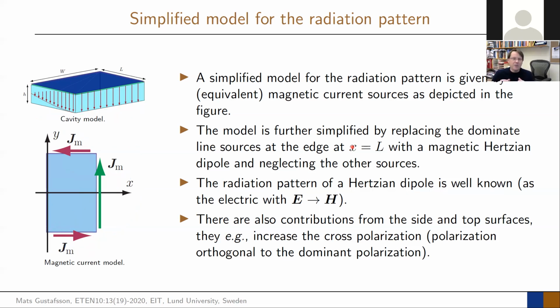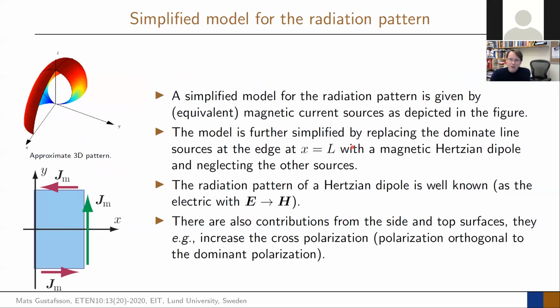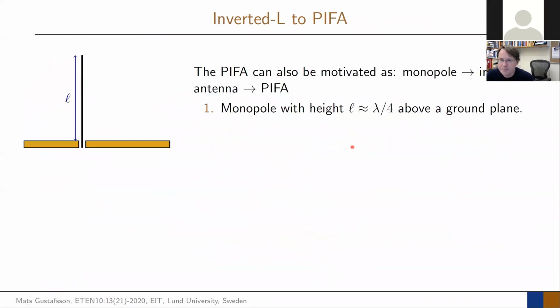Then when it's put on a finite ground plane, it starts changing because then it depends on the size of the ground plane. So again, here is the radiation pattern, and here we can see half of your donut type pattern, or this 8 pattern in some ways. So one dipole in this case that is directed like this. And then it is above the ground plane, so you take away the lower part, which then doubles the directivity when you go up. That is the radiation pattern that we have, which is quite easy to understand and actually see what that radiation pattern is.